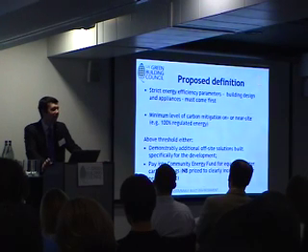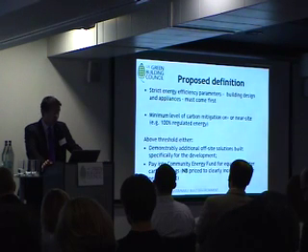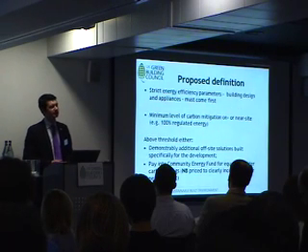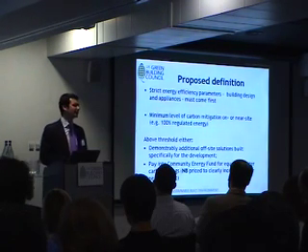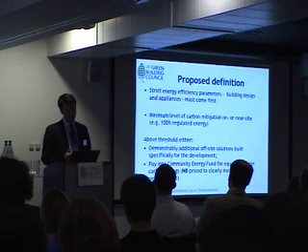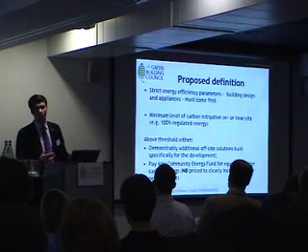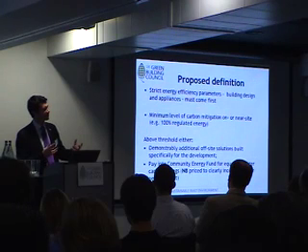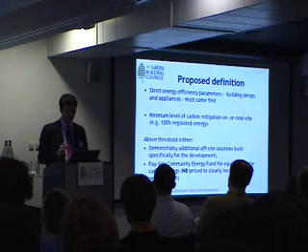Secondly, that you had to have a credible and frankly as high as possible minimum level of carbon mitigation on or near site. And for example, that could be something along the lines of 100% of regulated energy, which happens to equate to about code level 5. I refer you back to the discussion about how it's better to express these things, which is something that needs to be taken forward.